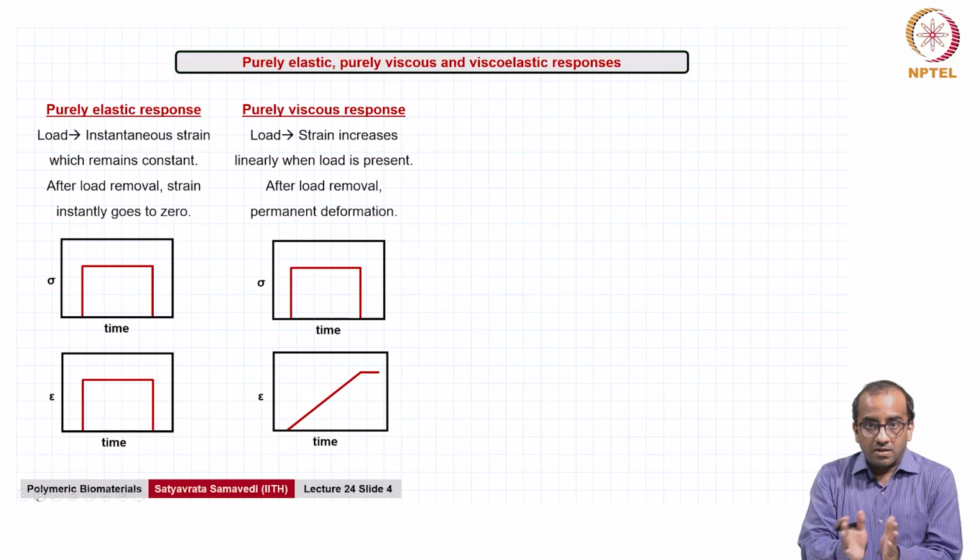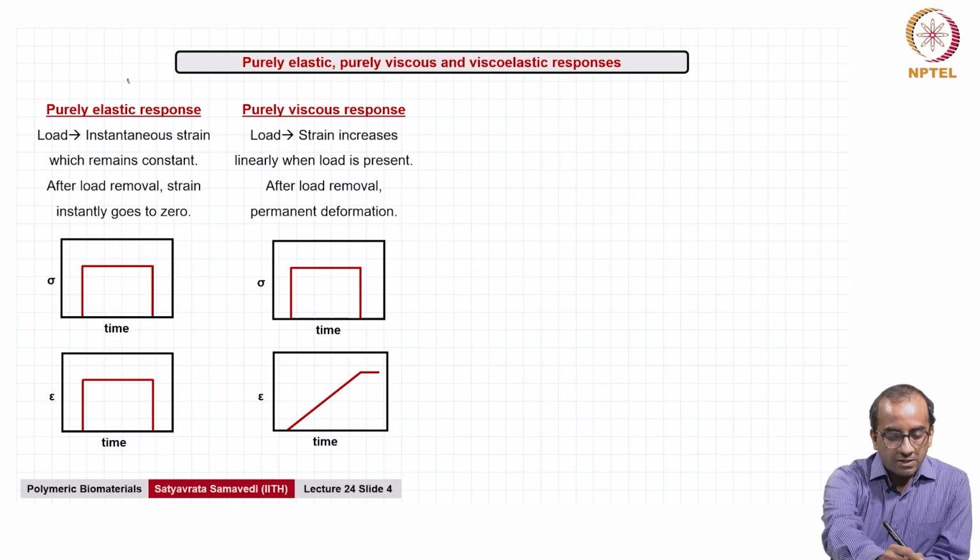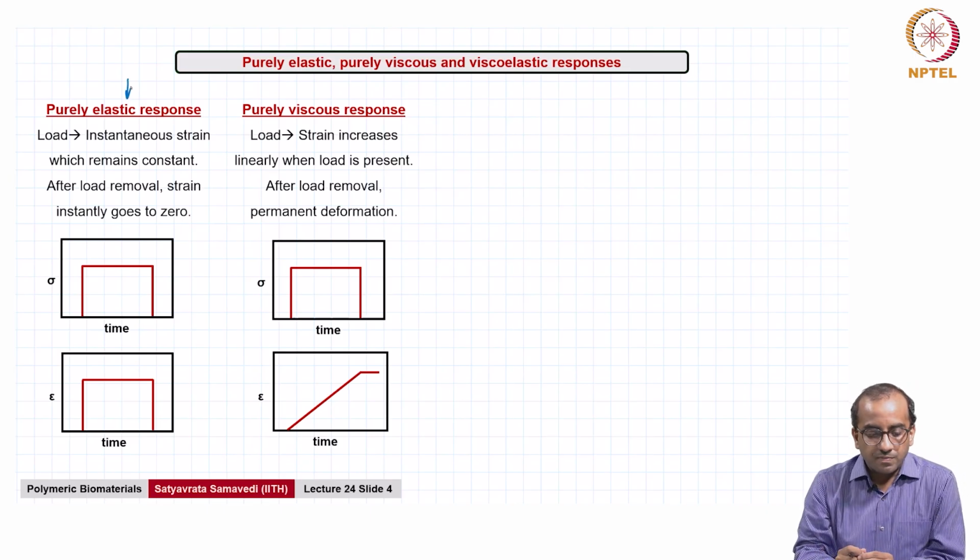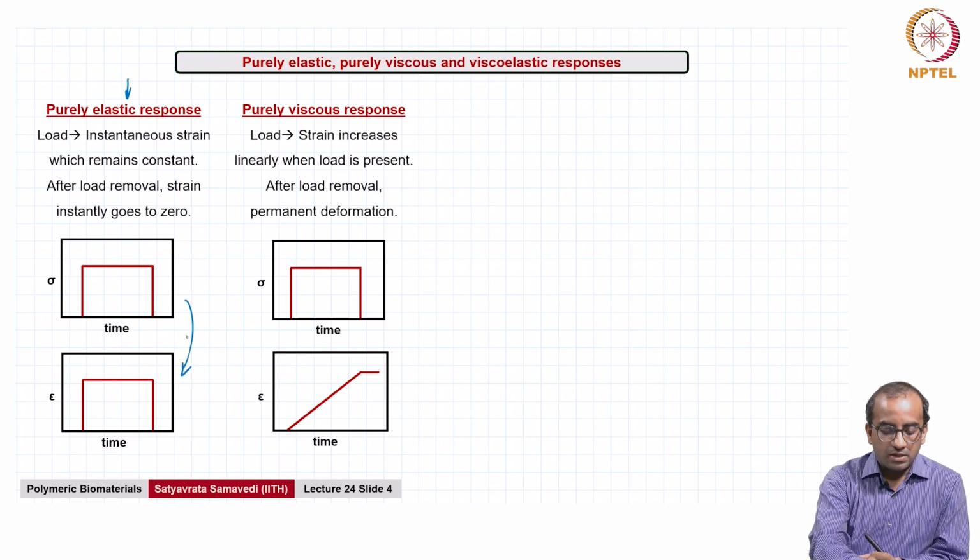So with that background, we now start looking at the responses of purely elastic solids and purely viscous fluids. Shown here are two extremes where in one case we are first looking at purely elastic responses, where a load is applied and, as soon as the load is applied, an instantaneous strain is achieved within the material which remains constant and persists as long as the load continues to be applied. That is what these two show.